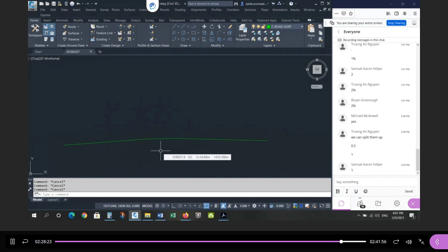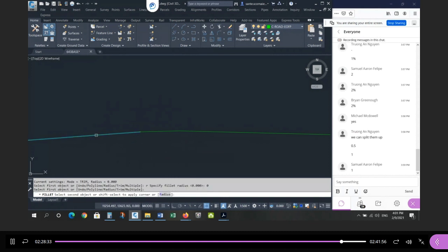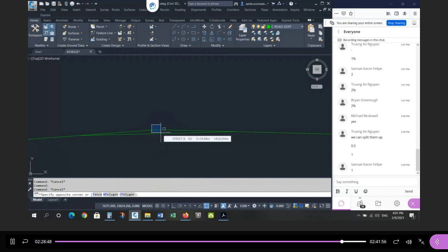Now, because I drafted the solution right there, I'm going to borrow the information I just drew. Watch this. I'm going to take a fillet with a radius of 0. I want the 1.5 to intersect the negative 0.5. And now this point is where the PVI is that has a 2% grade change, right? 1.5 positive, 0.5% negative, 1%, a 2% grade change.